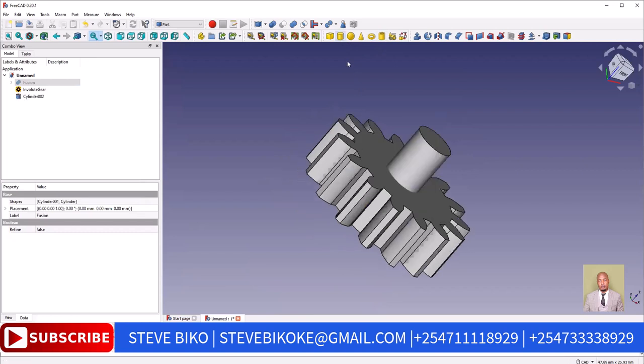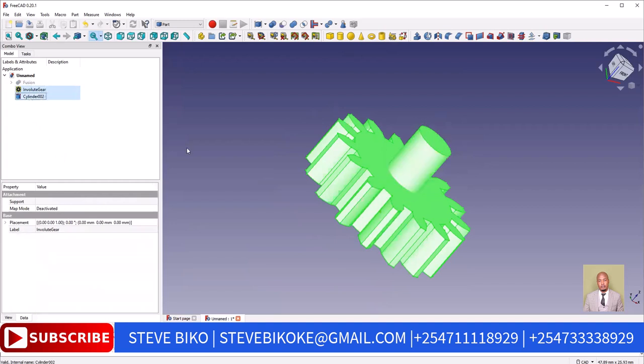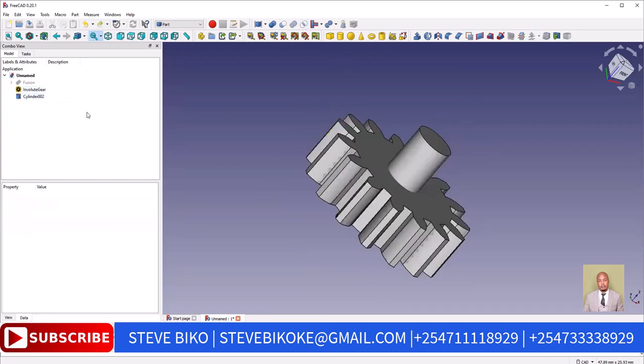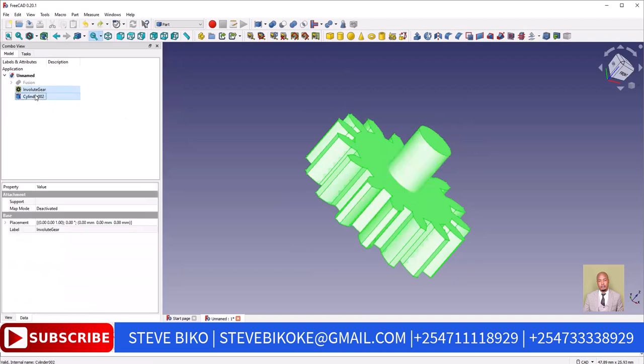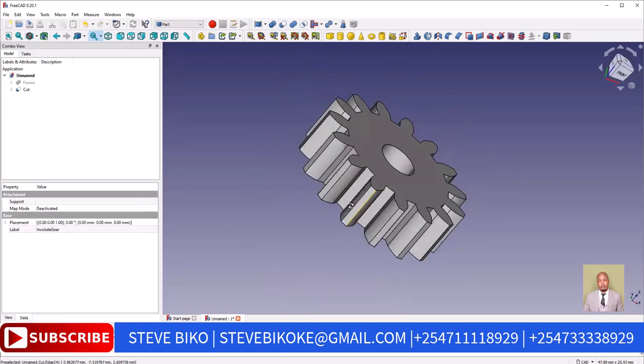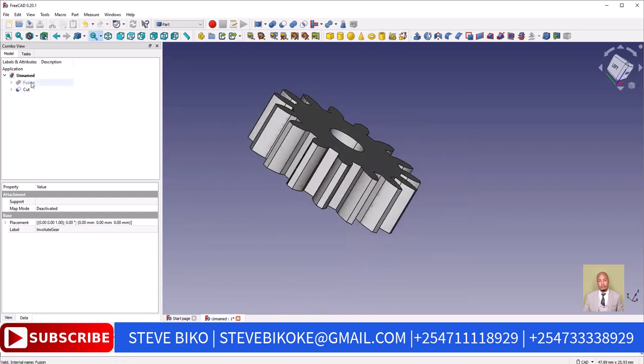We make a new cylinder. Select the gear wheel, control button, then select the cylinder, then cut it. Yes, we cut it using this one. The other one is a reverse. Now we have a hole in the gear wheel. And we can bring back our axle.